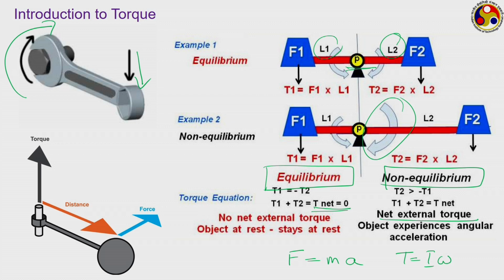Now, torque measurement is quite commonly related to the measurement of power, because whenever you are talking about a shaft rotating with a particular RPM and a torque is applied on it, we can easily relate the torque and its angular velocity with the power we can get from this shaft if we are talking about a power producing device, or how much power the shaft is absorbing if we are talking about a power absorbing device. So, whatever we are going to talk about regarding the measurement of torque is applicable to the measurement of shaft power. Dynamometer is the term used for any device commonly used for the measurement of torque.